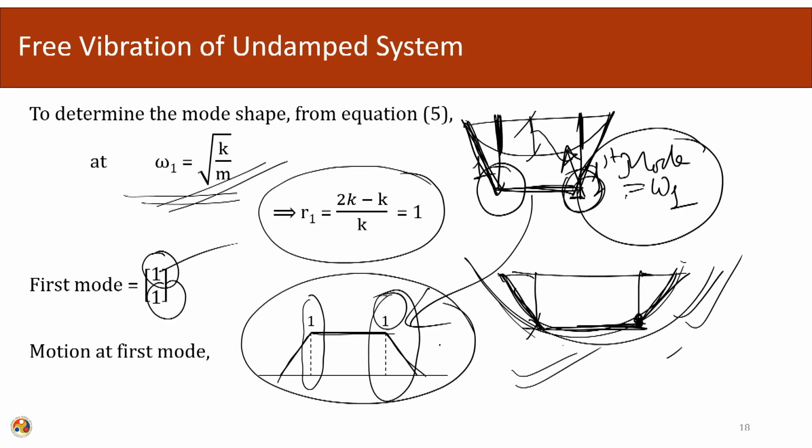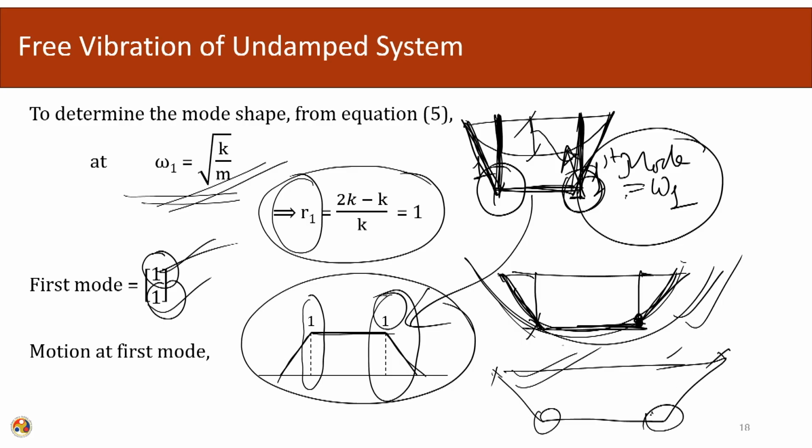After that we calculated the mode shape. For calculating the mode shape we use the amplitude ratios. So, amplitude ratios are coming 1 and 1. It means that if we take the beam analogy, if this chosen degree of freedom moves 1 unit, the other one is also going to move 1 unit. It means that it will do this shape. Since there are no masses in between, we model this as a lumped mass and the boundary condition has to be obeyed. So, 1 unit positive. So, this is the mode shape which corresponds to our earlier mode shape.